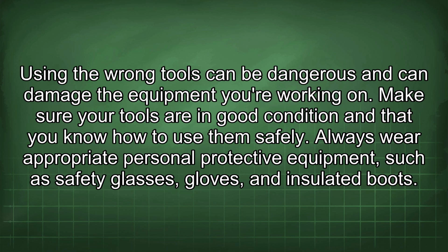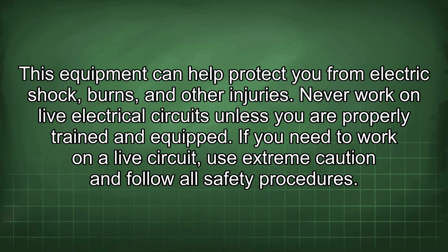Always wear appropriate personal protective equipment, such as safety glasses, gloves, and insulated boots. This equipment can help protect you from electric shock, burns, and other injuries. Never work on live electrical circuits unless you are properly trained and equipped.